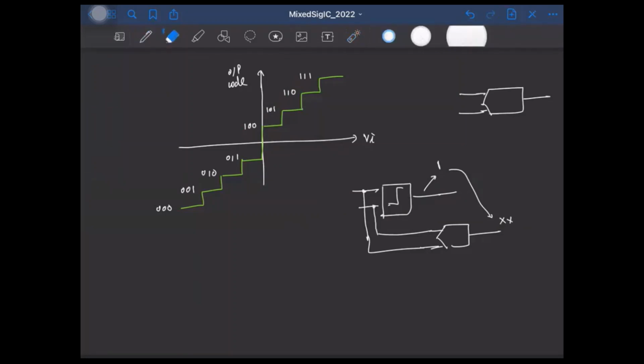And if the comparator output is low, we'll flip the input, right? So instead of giving the input directly, we'll give minus VI. Since here VI will be negative, minus VI will be positive, and this can digitize and get the input digitized properly.